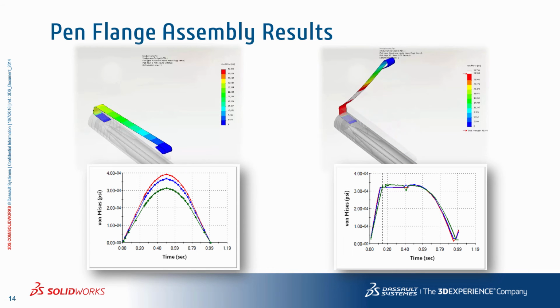Comparing the results clearly illustrates the vast differences in the shape, deformation, and overall response in the flange. The linear material overlooks the yield stress point and still uses the elastic modulus in the linear range to calculate the final stress and deformation. The nonlinear plasticity model predicts the correct response since it tracks when the material yields and what happens beyond that point in the plastic region. So when the load is completely removed, it accumulates permanent strains and stress in the flange, causing it to have a permanent deformed shape as illustrated in this video and also the graph below that video.